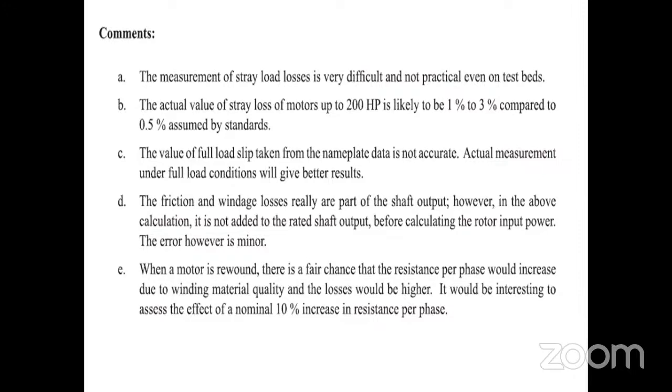Friction and windage losses really are part of shaft output. However, in the above calculation, it is not added to the rated shaft output for calculating rotor power input. The error, however, is minor.